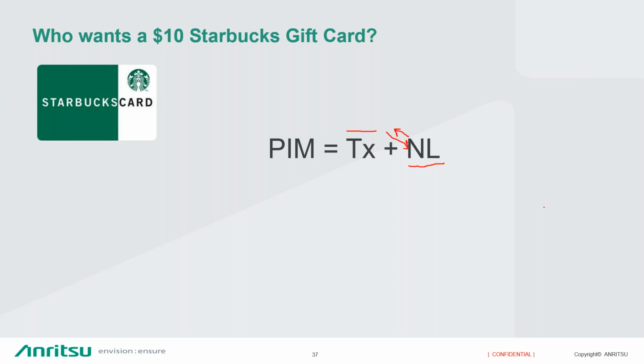Okay, we have just a couple more. For external PIM hunting, do you need a band pass filter? Yes. If you're doing troubleshooting, and it sounds like maybe I'll do a second webinar on the actual troubleshooting, you do need a very precise tone and a very precise spectrum analyzer that's calibrated to that certain IM product's frequency so that you can find the exact location of the nonlinearity. Hopefully that answers the question.